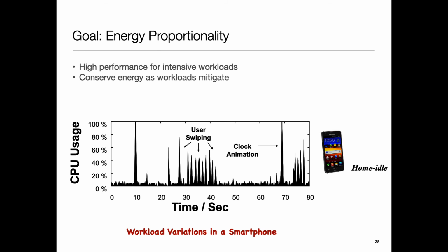And if you look at one of the new things on smartphones in the past 2-3 years, it has been adaptive refresh rates. Actually that's a cool project direction to also think about. So phones, the displays, the OLED or LCD displays, they have a refresh rate, and traditionally they were just a fixed refresh rate. But the display power depends upon the refresh rate. So one of the things that happened, I think starting 2-3 years ago, is that the refresh rate became adaptive.